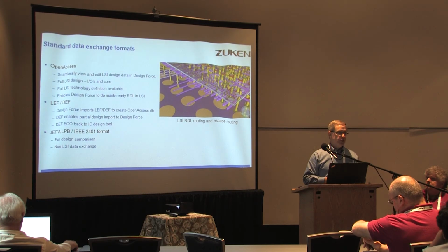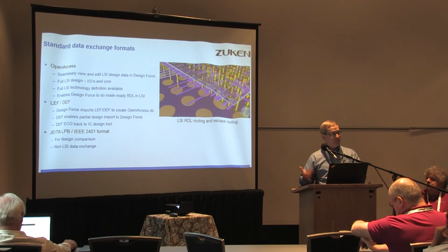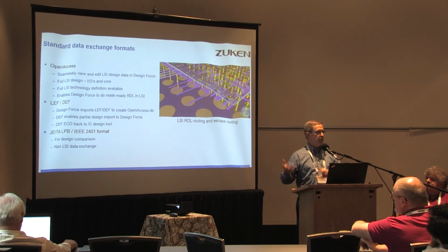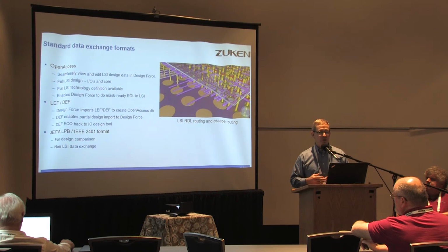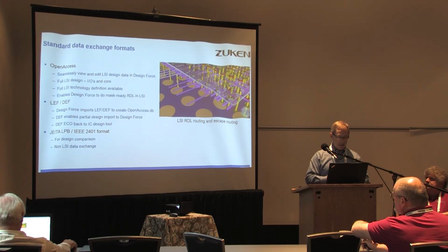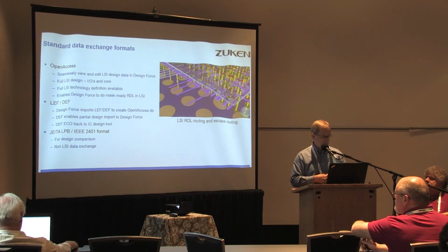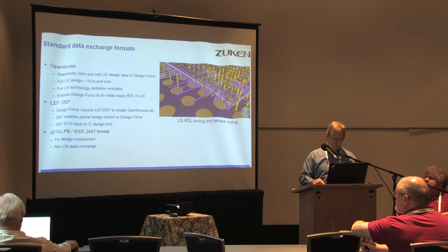Or if they need to do ECO back into an existing design, we'll dump out a DEF file. Many of the tools have ECO DEF capabilities that they're able to read those changes back into the IC design tool. We also use the JADA LPB or IEEE 2401 format for various operations in the flow. It is made to be able to define a full system, whether it's IC, package, board, and the connectivity between. We only use it for design comparison and non-LSI data exchange in our design flows.